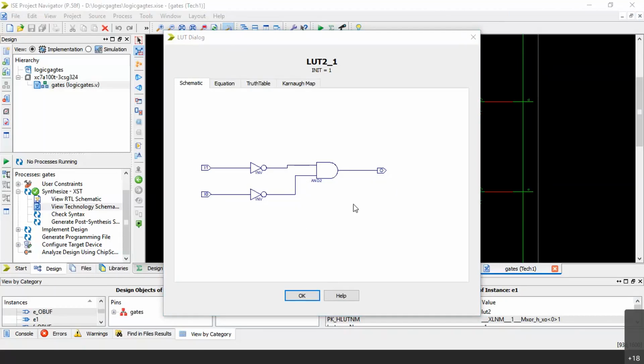Instead of a NOR gate, why is it showing an AND gate and inverter separately? The reason is inside Xilinx, there is only an AND gate, OR gate and inverter. That's all. Inside Xilinx, it can implement an AND gate, an OR gate, an inverter directly. If you want other gates, it will connect them this way. Anyhow, the tool is powerful, and in an FPGA there are thousands of gates. We don't have scarcity of gates inside an FPGA, so it does not really bother there.